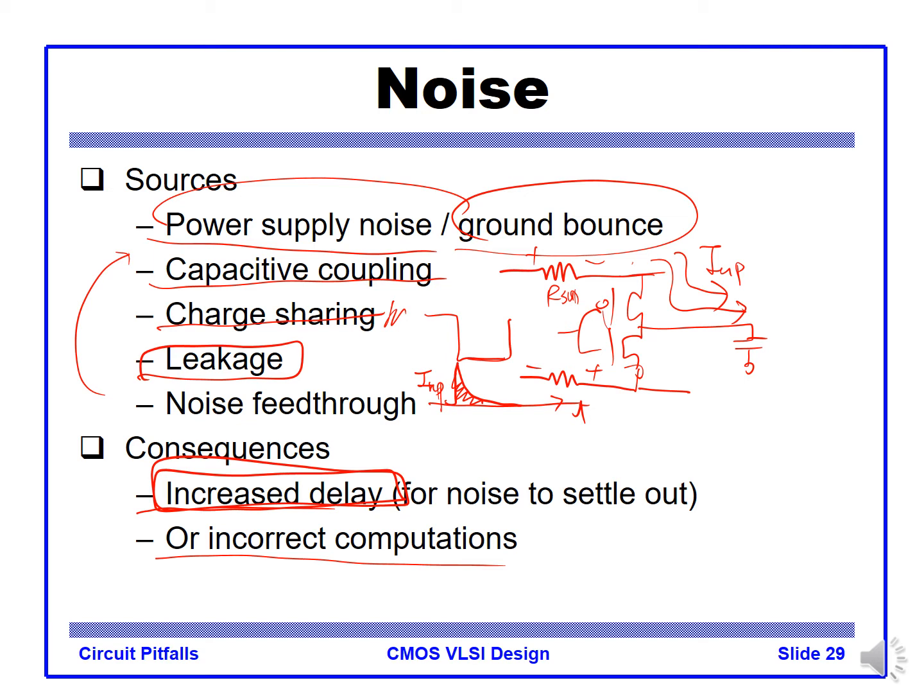So how do we model such margin? We may increase the clock frequency, or we may reduce the supply voltage, we may increase the temperature, so we can have a variety of different ranges of variables like supply, temperature, and clock frequency. Some kind of variation you can apply to your design and see whether your design is robust to such variation or not.